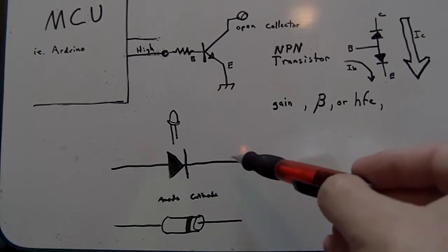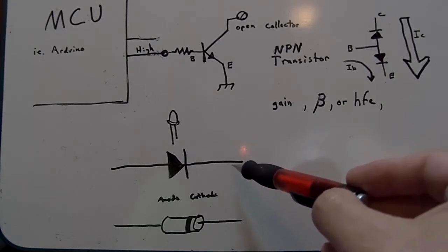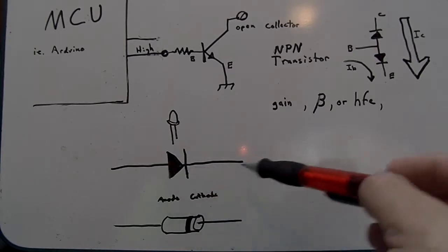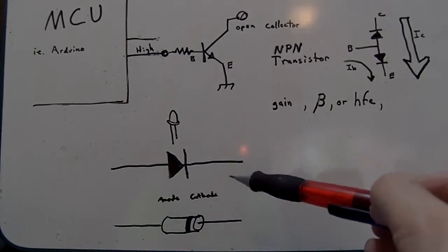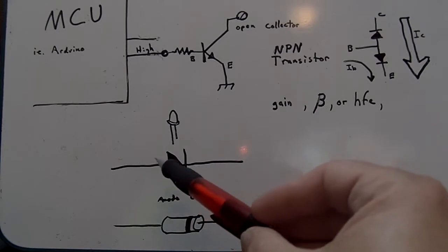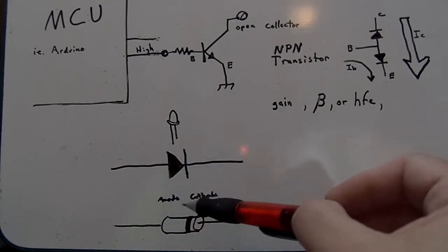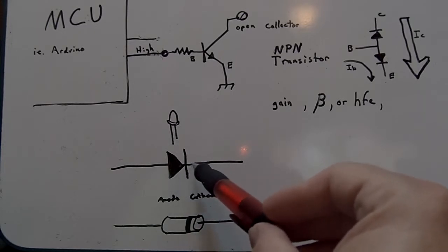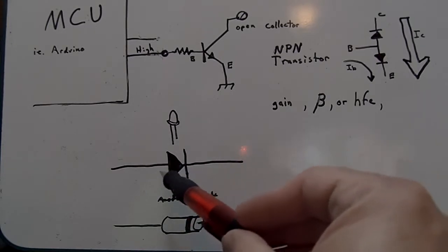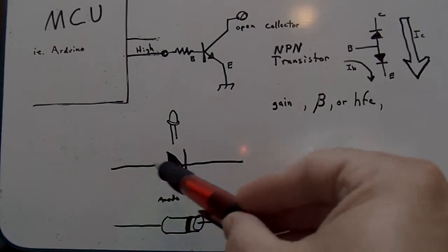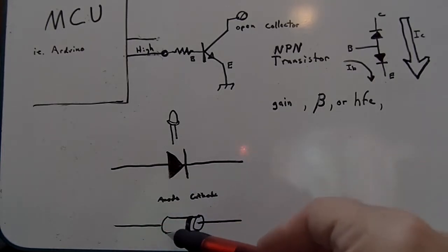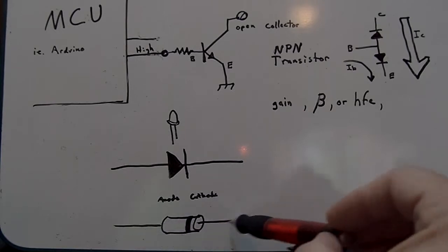A heavily rated diode, a real heavy-duty diode, at its maximum current flow, getting the thing physically hot, maybe it'll drop a volt in the forward. And then maybe if you're talking microamps at a real low end, maybe 0.5. But really, that 0.6 is pretty typical. If I'm flowing an amp or two through here, I'm going to lose about 0.6 across. Cost of doing business.